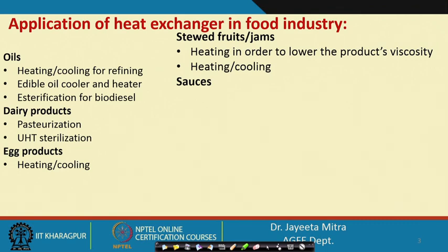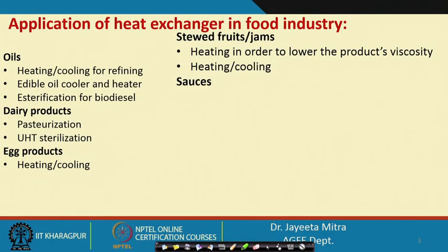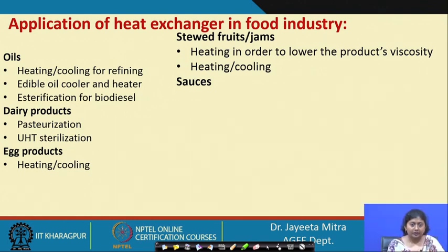Now, different stages of cleaning take place, so that no dirt or deposition should be there in the inner tube or outer tube, and if it is there, from that microorganisms may grow and spoil or contaminate the food. Okay. So sanitation is very important, and keeping that in mind, the design of the heat exchanger will be such that we can very well clean the material, because there are many dissolved particles or materials in the liquid, and their viscosity is also very high. So you need to pump them. Okay. So all those requirements we need to consider.